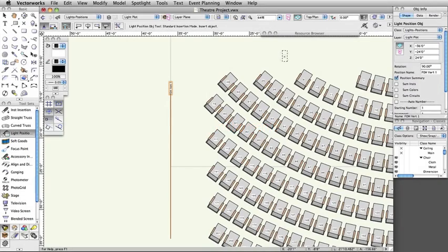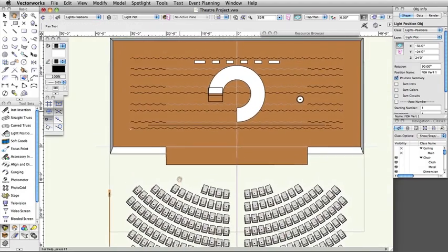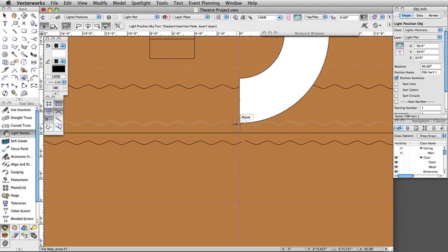Light instruments are made from symbols. Normally they should be hybrid 2D, 3D symbols. These symbols have separate 2D and 3D components. This allows them to be displayed differently depending on the view. At the very least, a lighting device symbol needs to consist of 2D screen objects. Creating custom lighting instruments will be covered in another section of this guide.